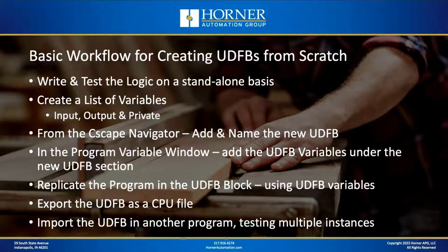Let's review the basic workflow for creating UDFBs. This is not new territory, but it's important territory. So here's our process. You always start by writing and testing the logic that's going to be included in the function block on a standalone basis. Whether you start with a blank slate or whether you copy and paste logic in from a different project you've done in the past and then edit it from there, whatever the case, you're going to want a standalone project or file, if you will, that you're going to use to write your logic and to test your logic.